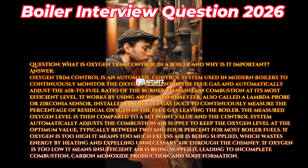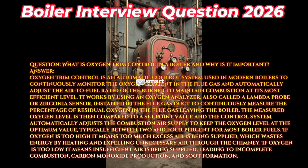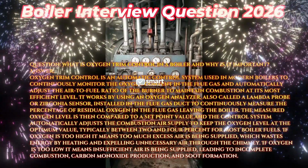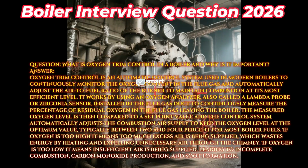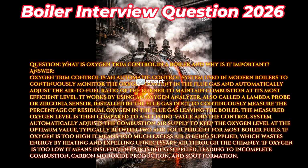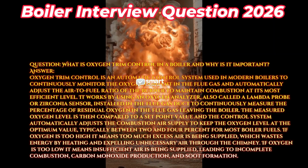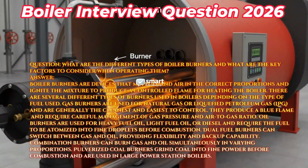The measured oxygen level is then compared to a set point value and the control system automatically adjusts the combustion air supply to keep the oxygen level at the optimum value, typically between 2 and 4% for most boiler fuels. If oxygen is too high, it means too much excess air is being supplied, which wastes energy by heating and expelling unnecessary air through the chimney. If oxygen is too low, it means insufficient air is being supplied, leading to incomplete combustion, carbon monoxide production, and soot formation.